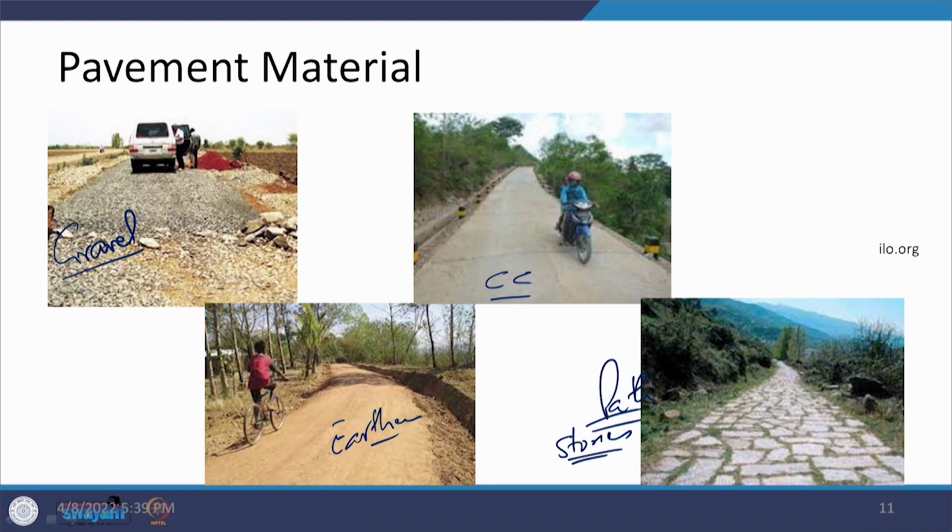As you can see here in this case, the friction is obviously going to be the highest. In this one the friction is going to be lower. If this earthen surface is well compacted and there is no effect of moisture, it is not making it muddy, then the friction can be lesser, but if it is becoming muddy, then the friction is going to increase. But if it becomes more muddy, then friction is further going to reduce, because now the slipping conditions are going to be there. So, it all depends on what amount of moisture is there in the earthen surface, which will further define how it is going to react in terms of the movement of a vehicle.